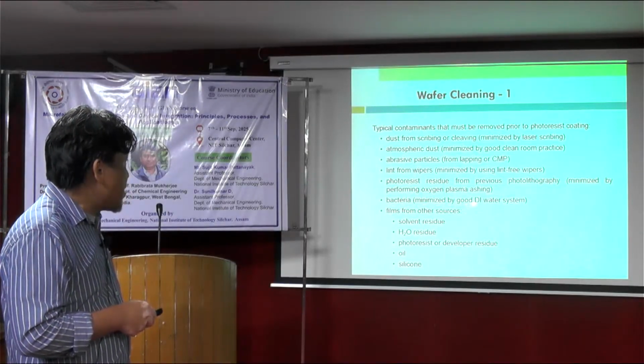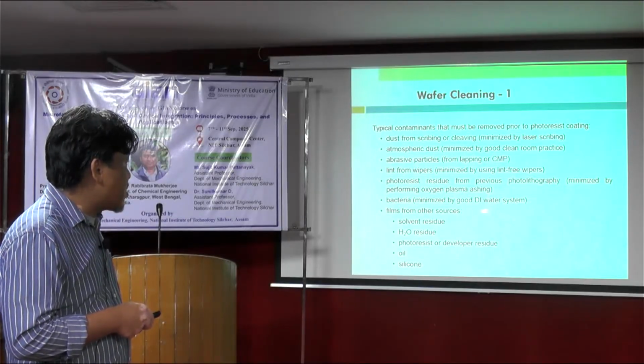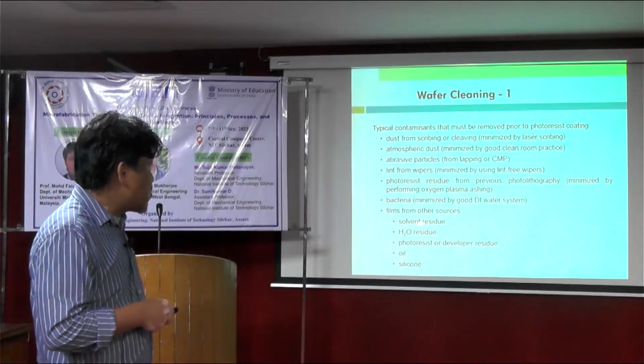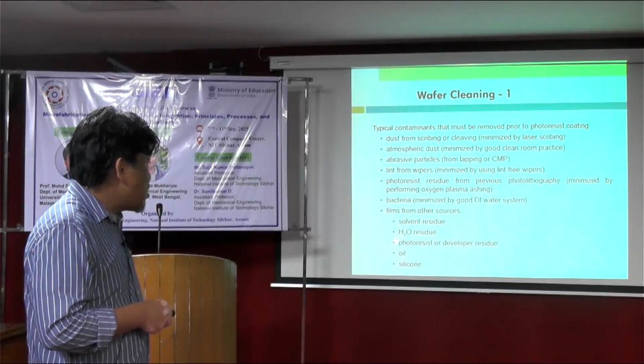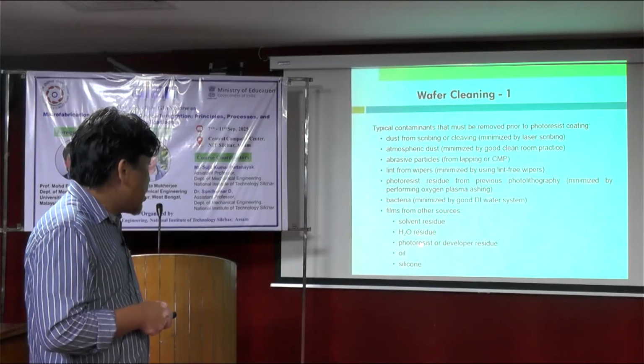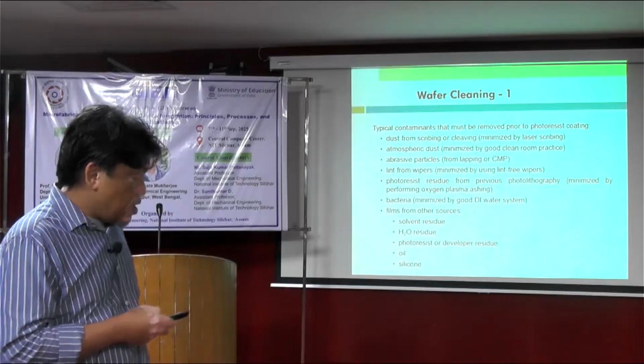Bacteria, minimized by good DI water. In the clean room, we use deionized water throughout the whole process. Film from other sources: solvent residue, water residue, photoresist or developer residue, oil and silicon as well.